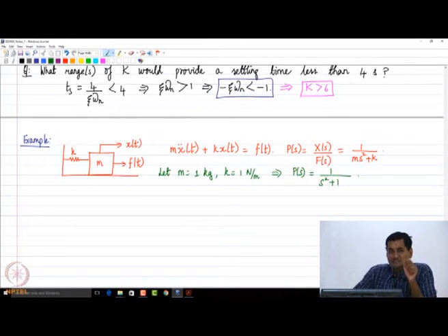So, what did we discuss? If you have non-repeating poles on the imaginary axis, then for one class of inputs the system output is going to blow off to infinity. So, in this example, for what input will your system output go to infinity in magnitude? Cos t and sin t, right. So, for imaginary roots, if you have a sinusoidal input whose angular frequency is the magnitude of the pole, our output magnitude goes to infinity as t tends to infinity. That is what we have.